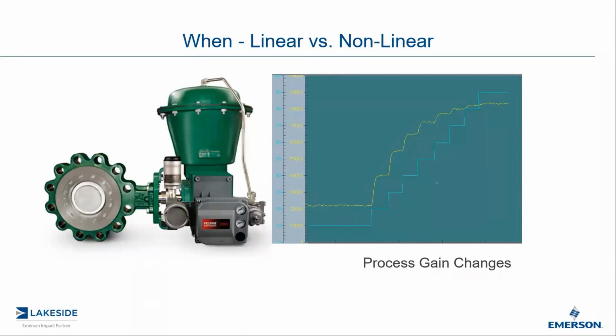Traditional butterfly valves are known to have a quick opening flow characteristic. As a matter of fact, some people in my crowd here may argue with me, but usually between 60 to 65% open or more, you're no longer controlling. You're actually in this area over here. You're no longer controlling. And at the bottom end, it's very, very sensitive.